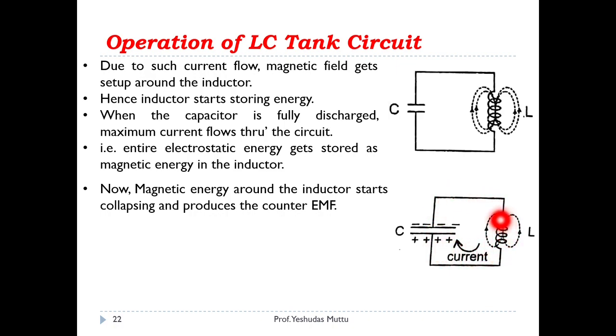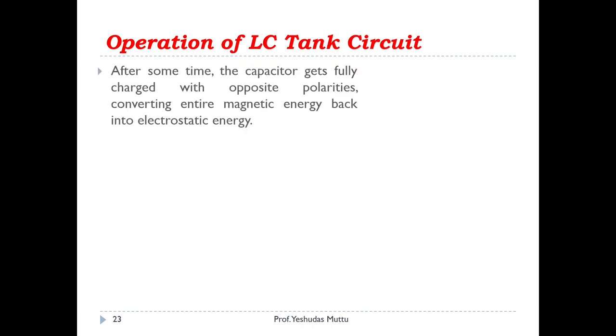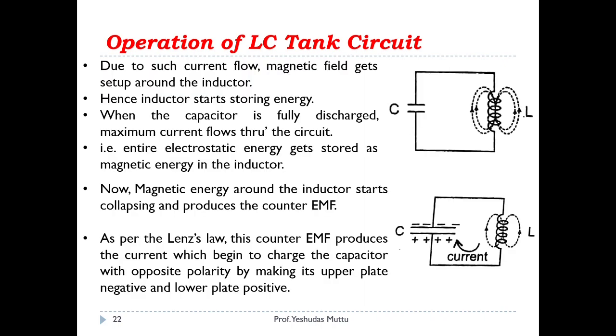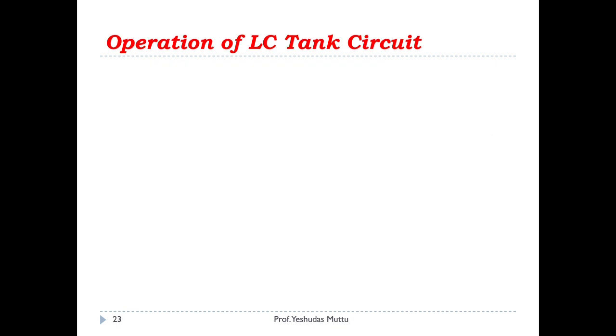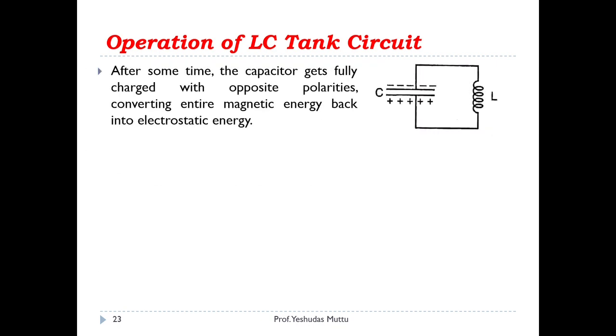Meanwhile the inductor is unleashing its energy, and the capacitor is getting charged. This counter EMF is set up only because of Lenz's law, if you remember, the basic principle of the inductor. Now when the inductor has unleashed its energy, the capacitor is fully charged but in the opposite direction.